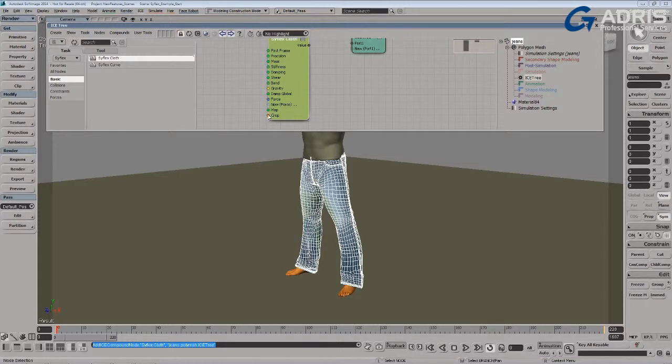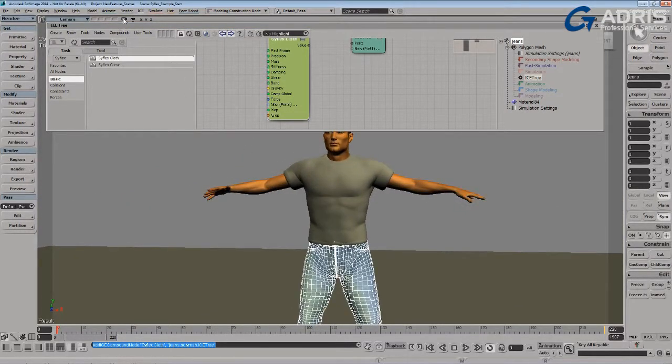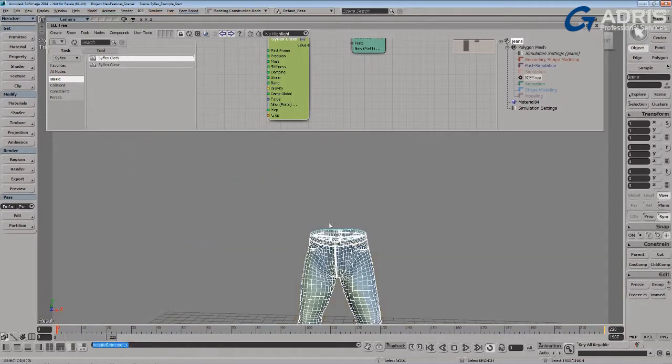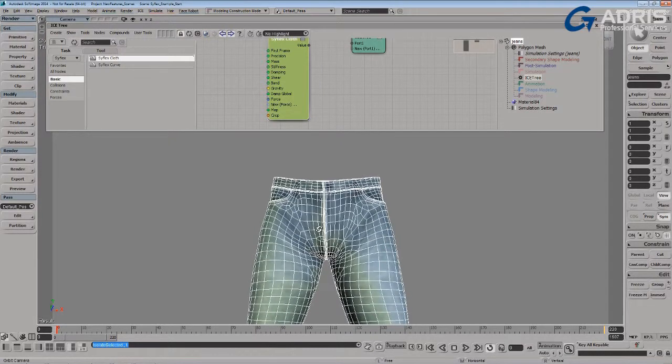One is the ability to crop out the effects of a cloth simulation, so they don't have any effect on those points. Essentially, this is just a Boolean attribute where you use the is element to essentially just mask out the unwanted area. In this case, I'll just isolate the selection. This has the effect, of course, of speeding up the simulation.